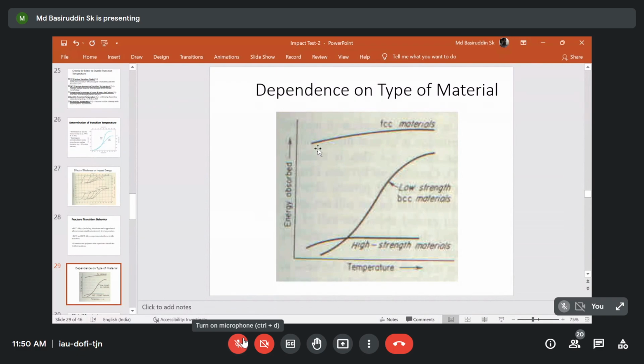Why is it insignificant? That is the big issue, and if you want to go into details, there is a vast metallurgy available. FCC materials are very soft, and the slip system is significant, meaning close pack slip planes and close pack slip directions are there, as compared to the BCC material.